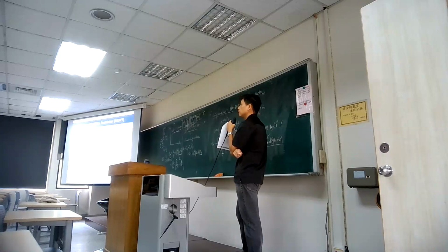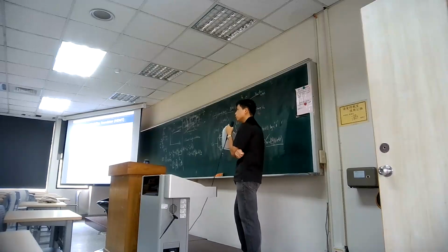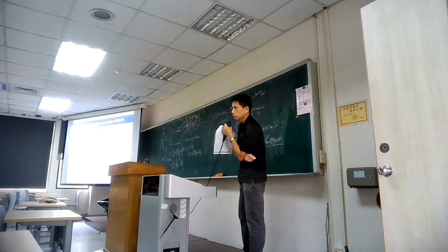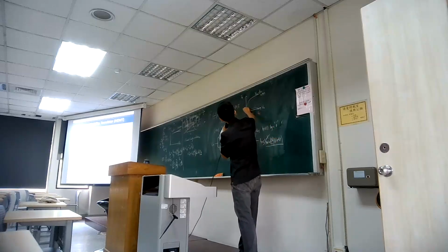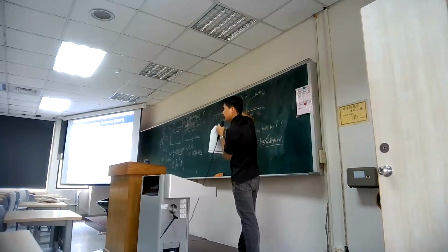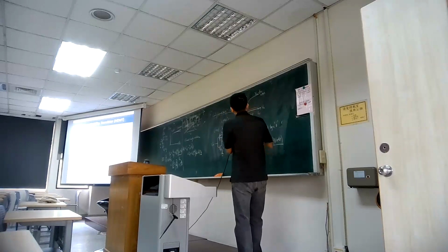It is in the triode region. Okay, remember what I said before. If you want to work with logic circuits, we want to use the cutoff region and the triode region. In BJT mode, it will be the cutoff region and the saturation region.